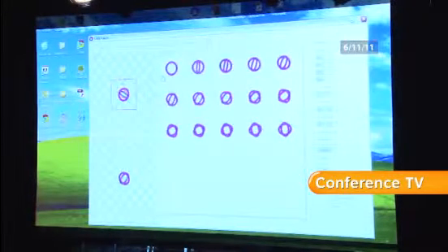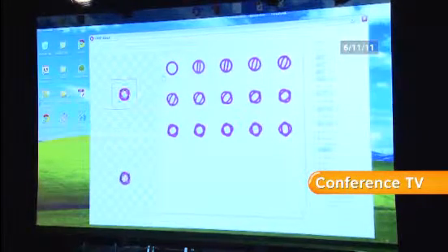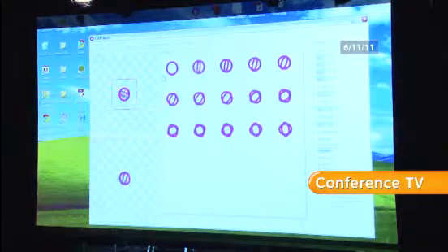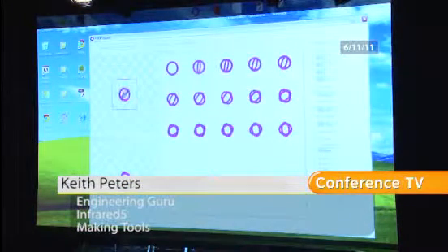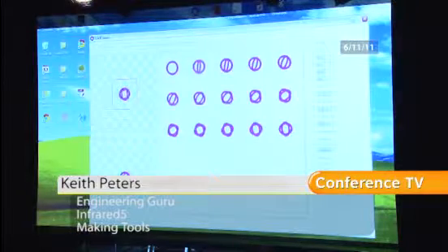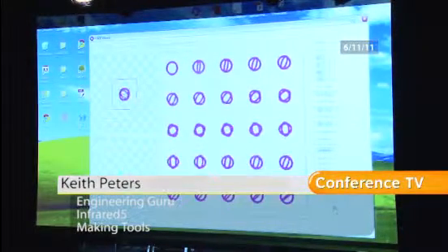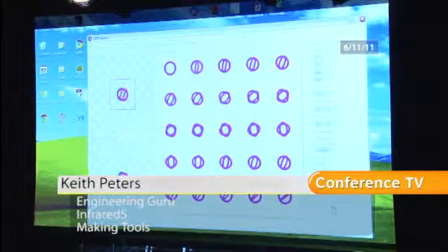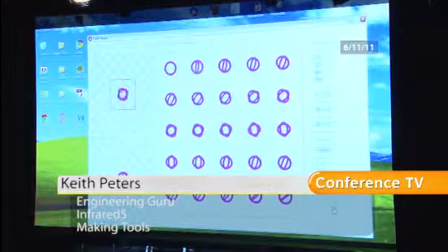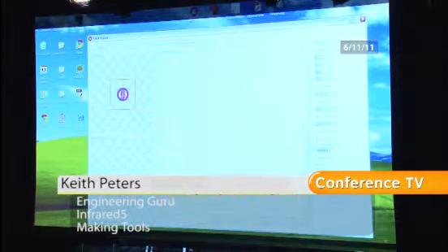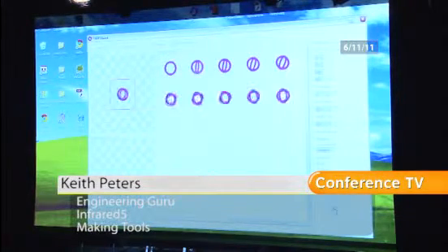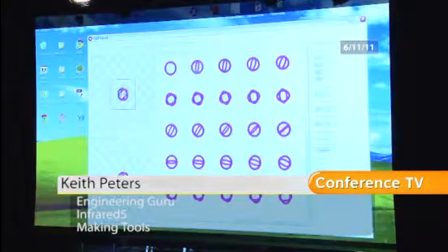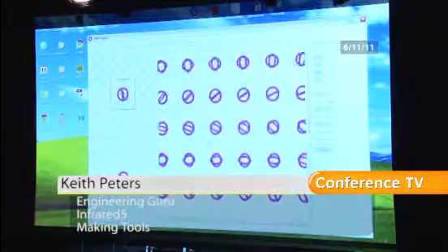Now the problem here is that I know this animation has 60 frames, but over here we're only showing 15 total frames. So the first thing we need to do is correct that to 60. Now if we recapture, well now you see our bitmap isn't big enough because it only holds 25. So we can do two things. We can make a larger bitmap down here, and now that's fine because now it holds all 60 frames.